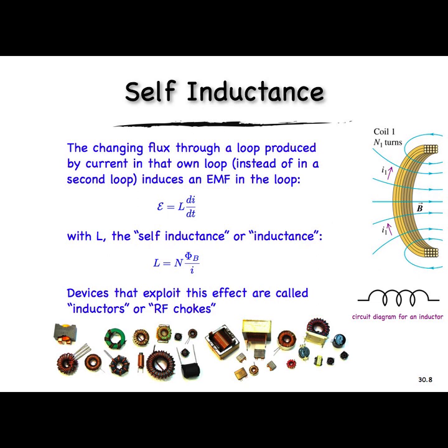So these numbers are fairly large. 5 amps is a lot of current. A household circuit can deliver about 15 amps before it blows its fuse. 1,000 turns obviously is a fair number of turns. A 1/2 meter long device is something that's not going to fit on a circuit board. And all of that gives me an EMF of only 47 millivolts.